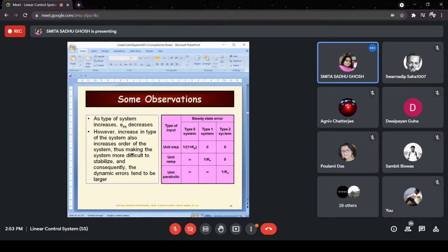If you have a step response which is highly oscillatory, it obviously implies that it is relatively less stable compared to a response which has fewer oscillations. Say, for example, it oscillates for 2 cycles before settling to the steady state value, and a system which oscillates 100 times before settling. Naturally, you can understand that the system which oscillates more is less stable.